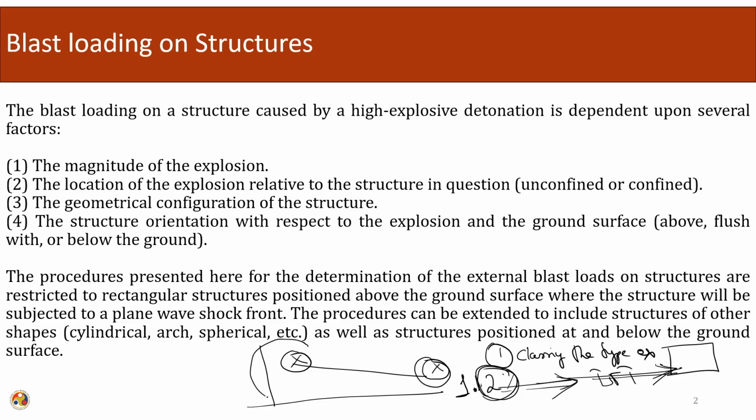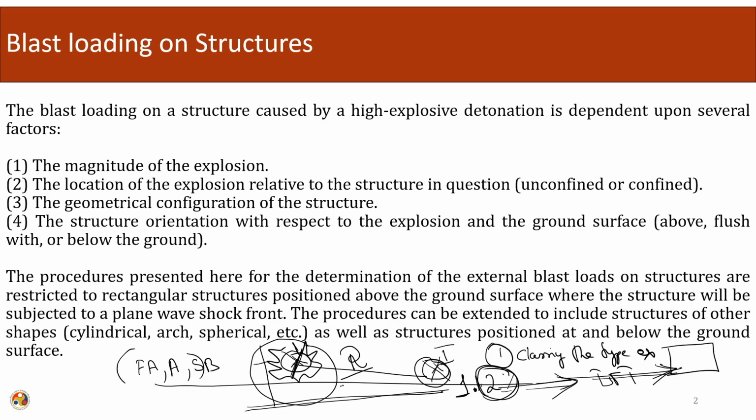After that, we need to categorize the type of the blast depending upon the location of the blast relative to the surface, the location in the air. We can classify it as a free air burst or a surface blast. After we have categorized these quantities, we need to calculate the distance between the point of interest and the point where the blast load is occurring. So we need to calculate the standoff distance.